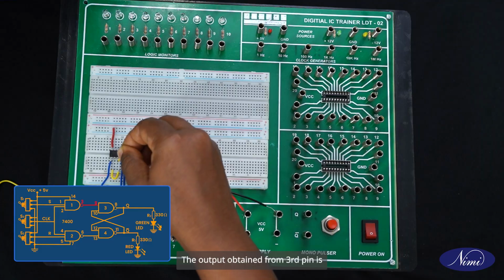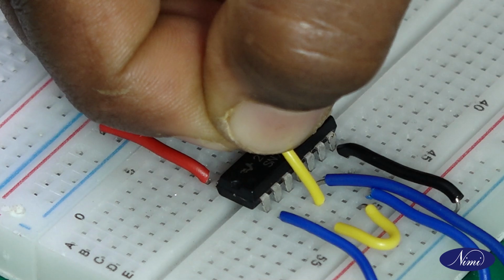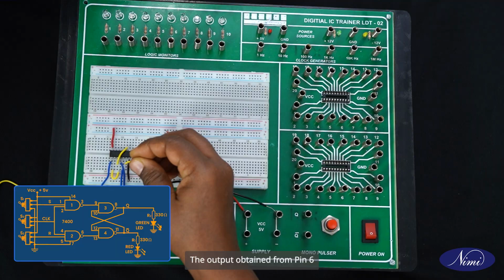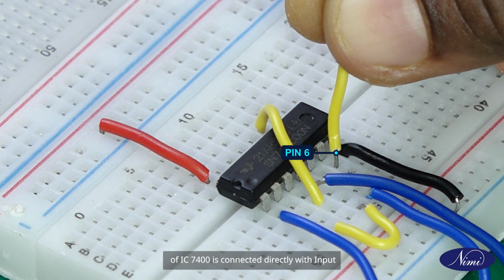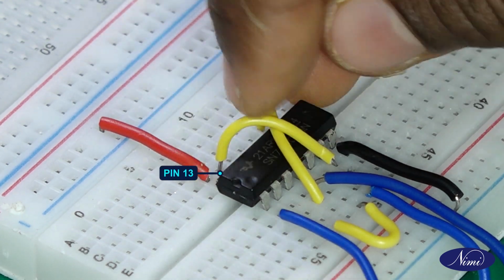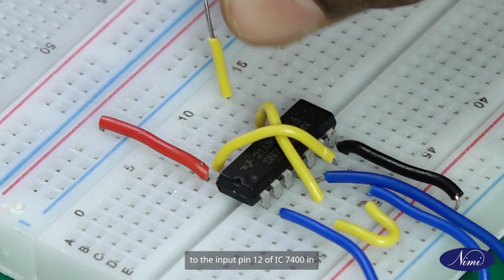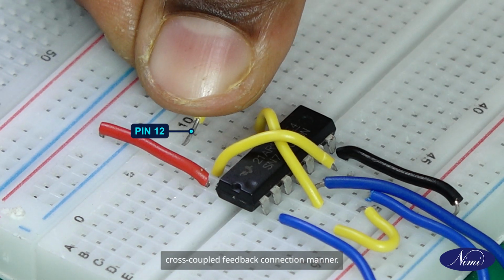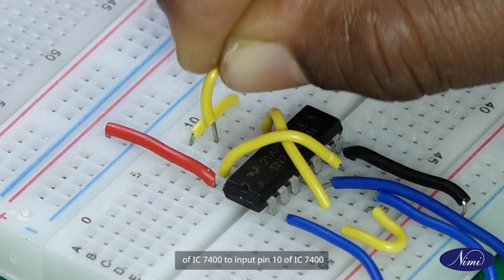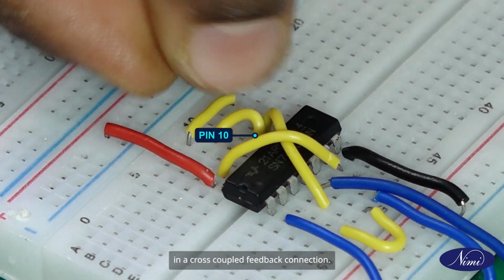The output obtained from the third pin is connected directly to input pin 9. The output obtained from pin 6 of IC 7400 is connected directly with input pin 13 of IC 7400. Connect final output Q pin 8 of IC 7400 to the input pin 12 of IC 7400 in cross-coupled feedback connection manner. Connect final output Q bar pin 11 of IC 7400 to input pin 10 of IC 7400 in a cross-coupled feedback connection.